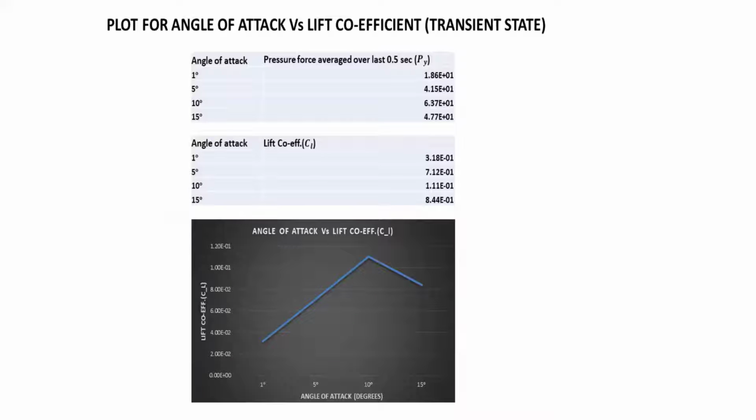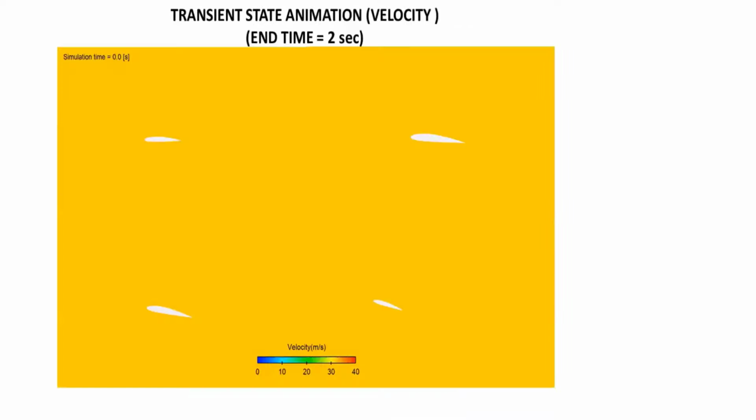Now it is increasing, till 10 degree it is increasing. If you are increasing the angle of attack more, lift is decreasing. Now that is what the stalling is. So you have to basically talk about stalling in your report and all, right? Because that is what we are focusing on. Okay, my drag force is increasing continuously, but after 10 degree my lift force started to reduce. So what's the benefit of burning a lot of fuel, right? So that is what in industry people are looking for.